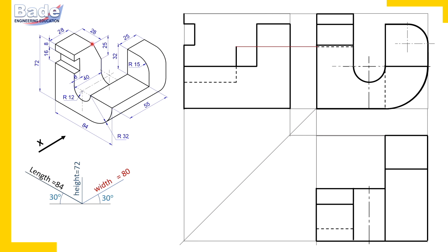You cannot draw a non-principal edge directly. You cannot draw non-principal edges directly unless you have two ends of that edge. So this principal edge is 28 millimeters long here. And once you draw all the principal edges, you will be able to draw non-principal edges. That is, simply join these two corners. So this is how we have completed this surface.